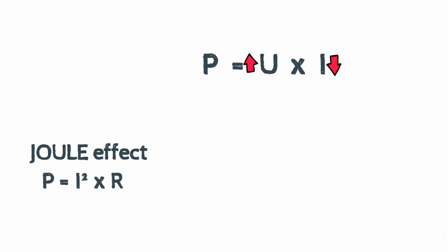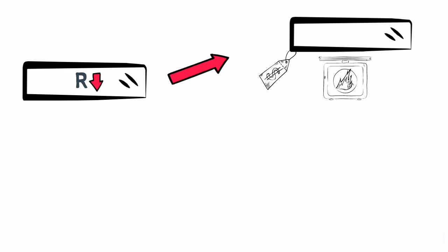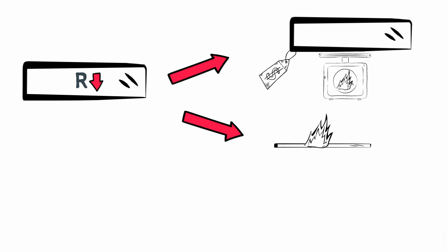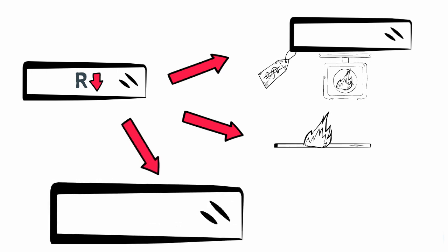The only other way you could avoid the loss is by decreasing the resistance of the cable. You may know that when you use cables to conduct electricity, if it's not a superconductor, the cable will resist, like a classic resistance. And trying to reduce the resistance will lead to a heavier and much more expensive cable with better material, or a cable too tiny that will melt. So instead, why don't we just reduce the current and increase the voltage?